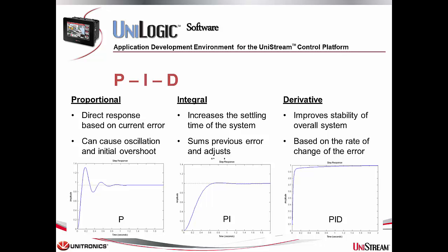Integral control will adjust not only the magnitude of the error and drive the system to the set point faster, but also the duration of the error. The action is calculated by summing the previous errors over a given time interval and producing an output from this sum. In turn, the integral accumulative action can recognize how the system has reacted previously and reduce the current error. In other words, it will allow the system to settle around the set point faster and reduce the error.